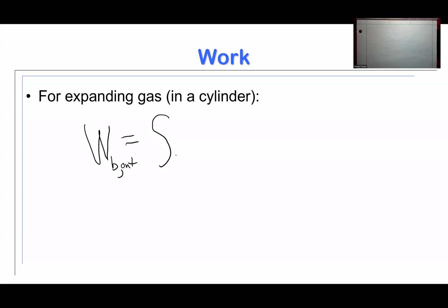And if we compute it in the out direction, that means we will be computing the result of pressure causing the force. Now, of course, pressure is force per unit area. So force would be pressure times area. And if I take area times distance, I get volume. So pressure with respect to volume, the pressure is what actually generates the force inside a system or external of the system. And the change in the volume then represents the change in distance for our system.